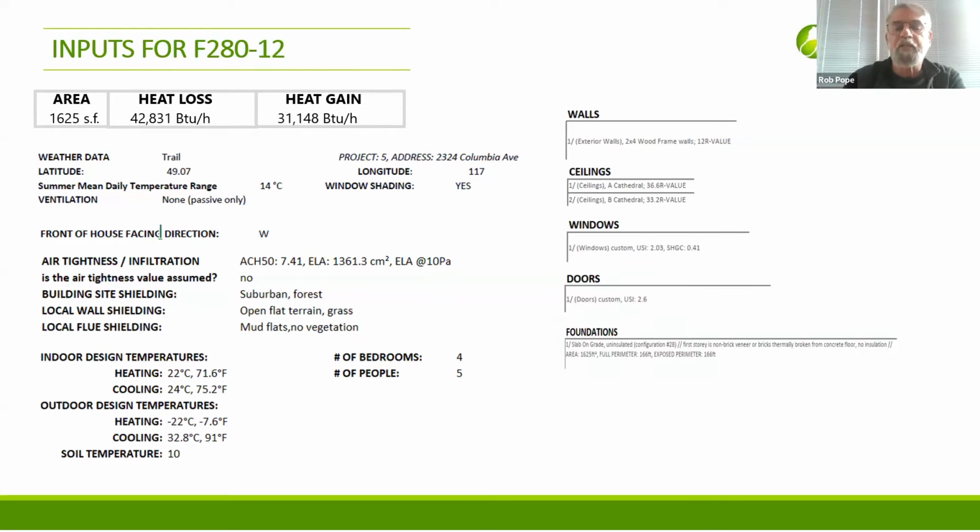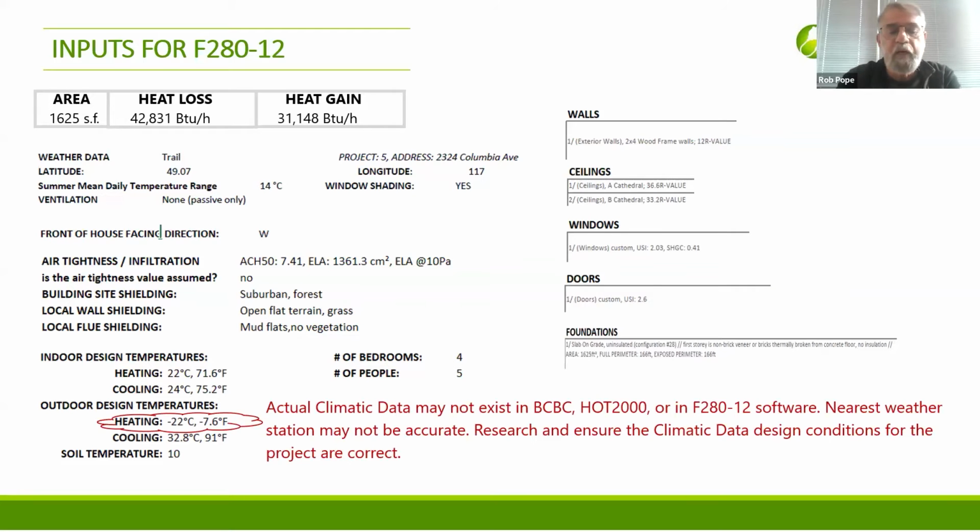Again, we measured walls, ceilings, windows, doors, foundations. We can see here what the indoor and outdoor temperature design conditions are, and number of bedrooms tells you what the people load, occupant load is. Here's one of the first things that was flagged.